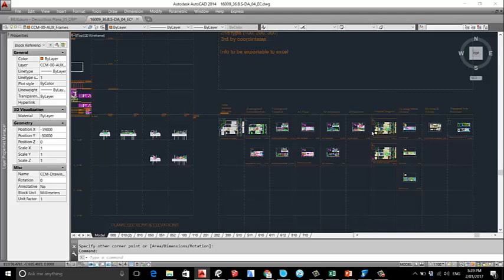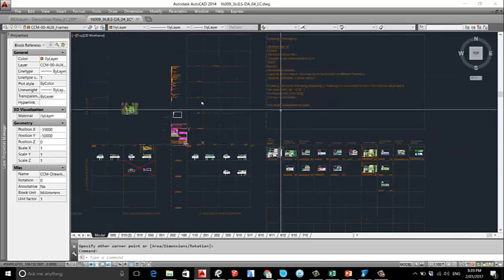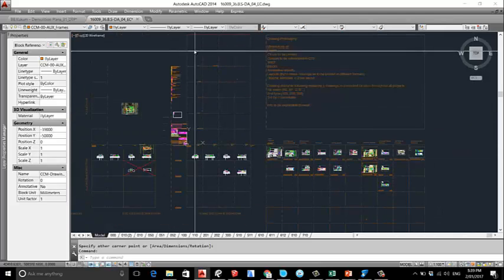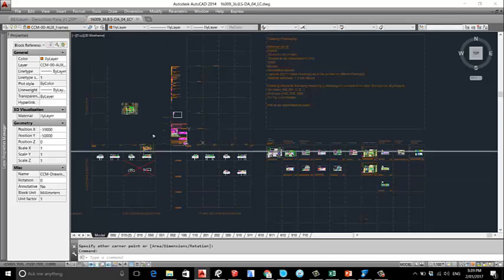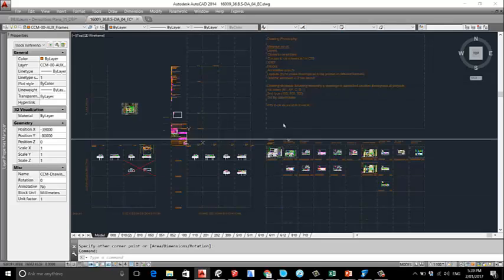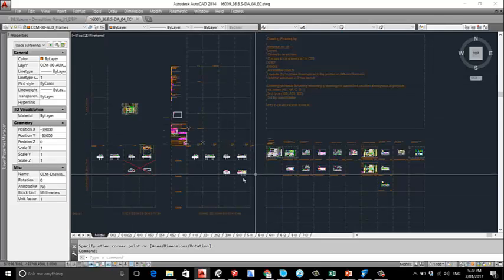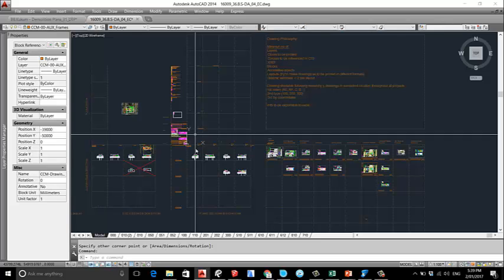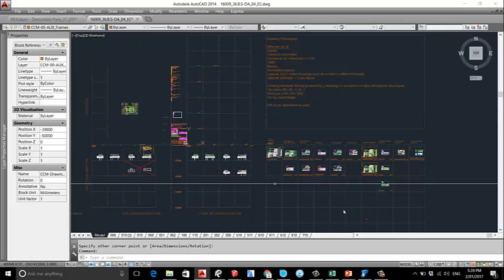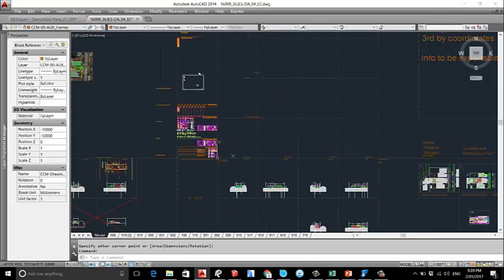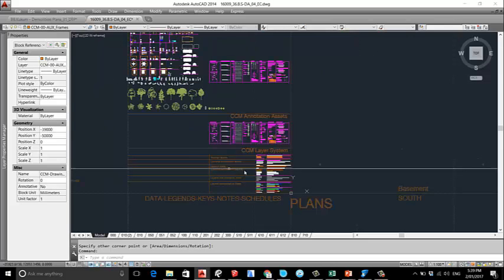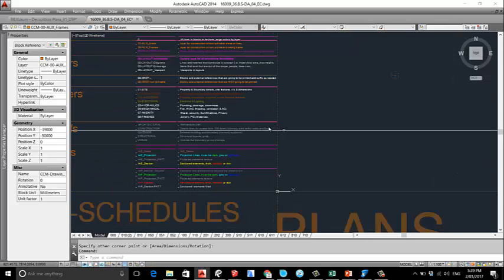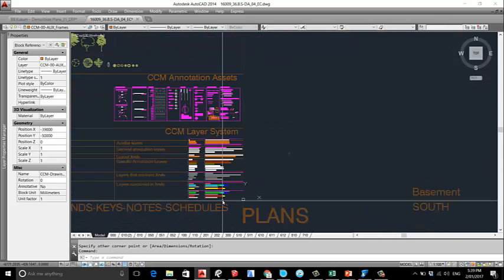So the idea is that, for example, this would be a good example. We don't have the floor plans because they might have been worked in another file which has nothing but the floor plans. But having the grid and the location for every drawing, we know that we could merge the drawings and nothing will overlap on top of each other. So the only common thing with the drawings is actually the grid and this center column I haven't covered yet, where we have the layers that we use.